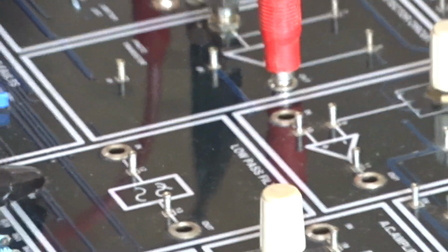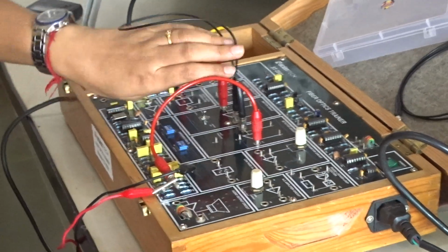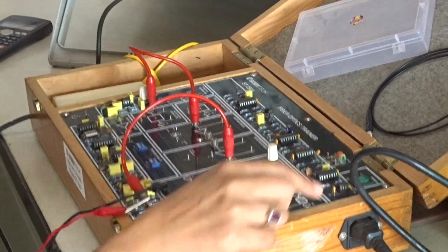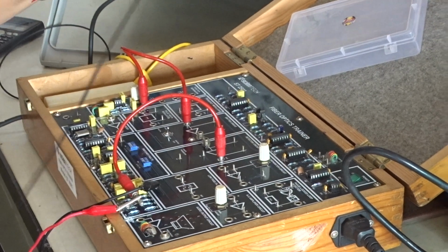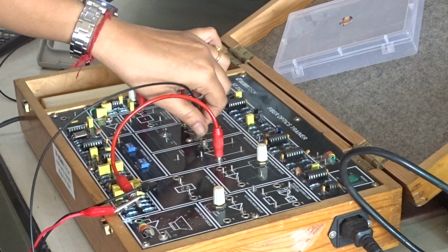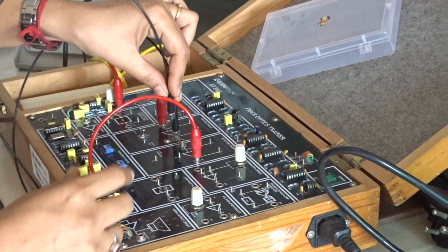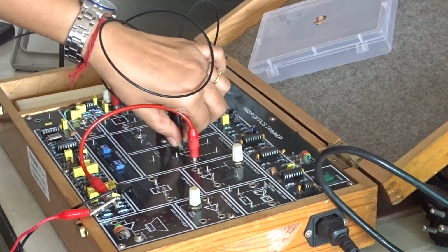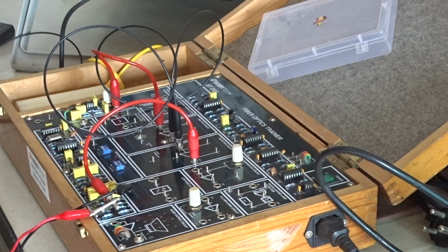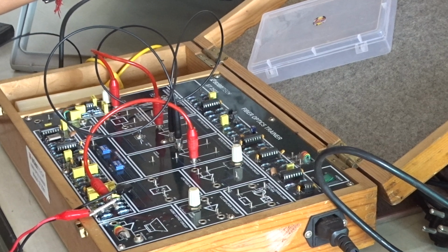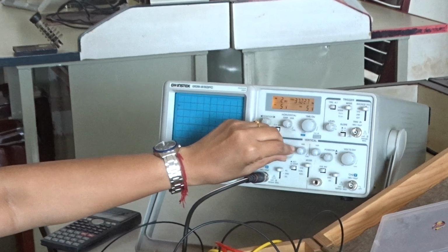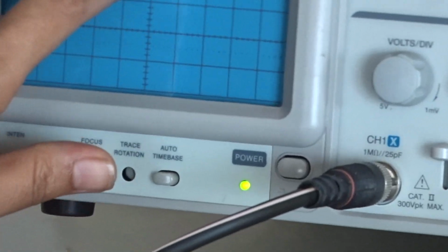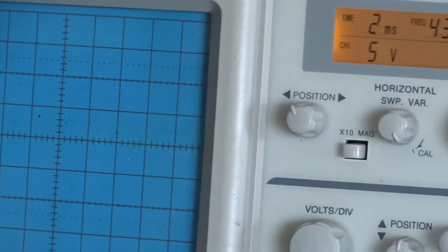Second step, to measure the attenuation loss we want the V2 voltage also. V2 will be obtained by replacing the previous optical cable by the 1 meter cable. The concept behind this experiment is, as you increase the length of the optical cable, the losses will increase, so the voltage must decrease. Now you can observe the output voltage is not equal to 5 volt; instead of 1 volt, it has changed to 0.7 volt. 0.7 volt into 5, you get around 3.5 volt, V2.